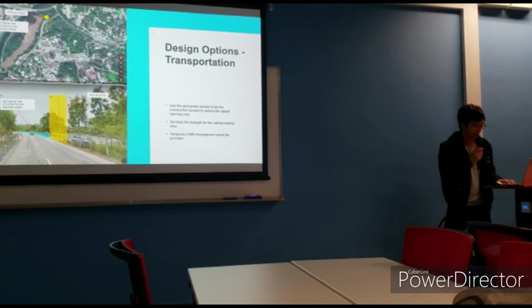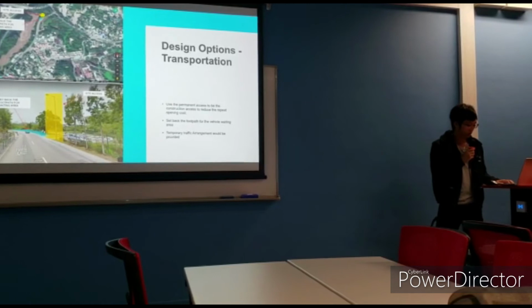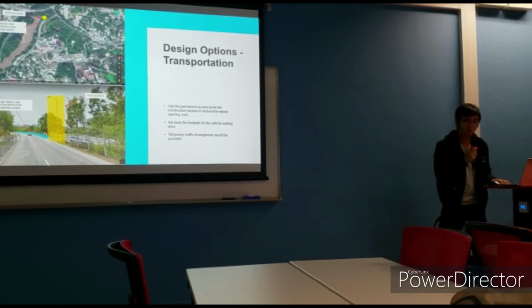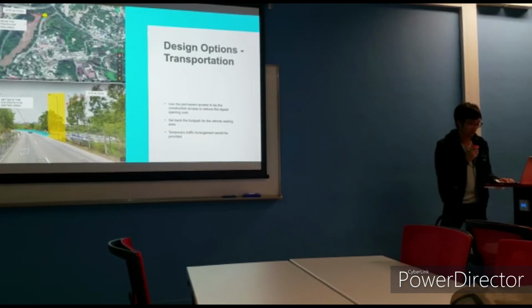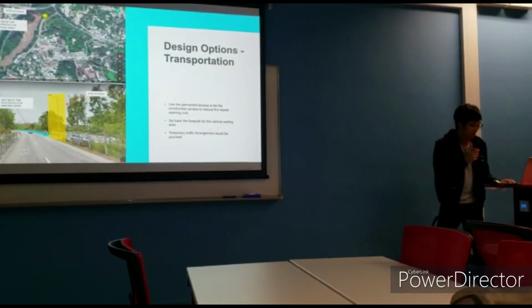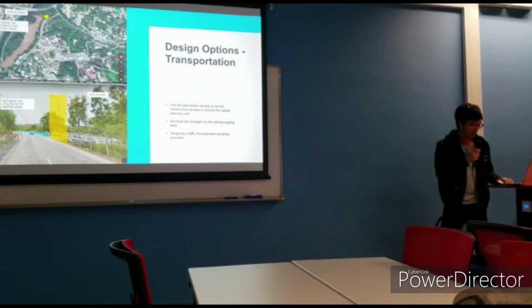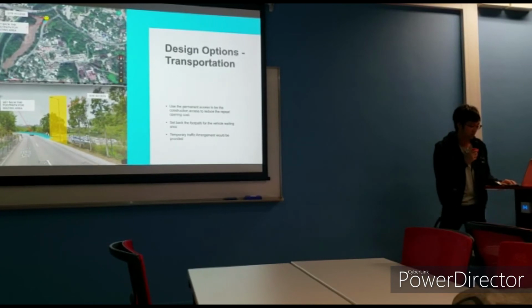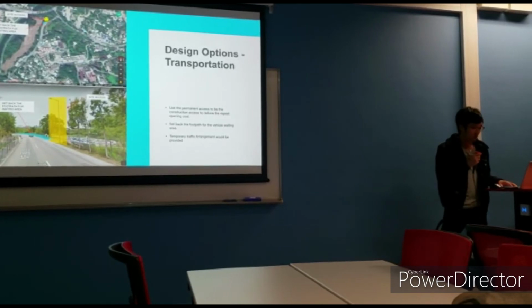The access is far away from the labor houses, but the home toll road is a one-lane, two-way road. Our access is close to the end of the turning. It will easily cause traffic accidents. So we would like to propose to set back the footpath to form a waiting area for the construction vehicles, and temporarily divert pedestrians to use the opposite footway. It can reduce the effect on the labor and be safer, as there will be many heavy vehicles in the construction stage.